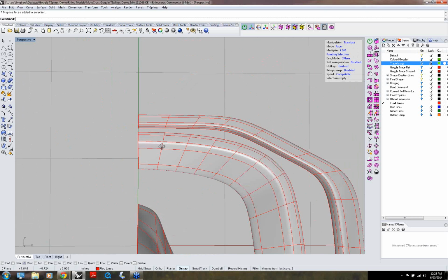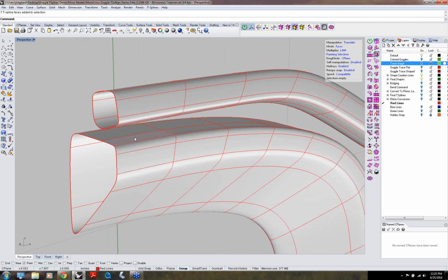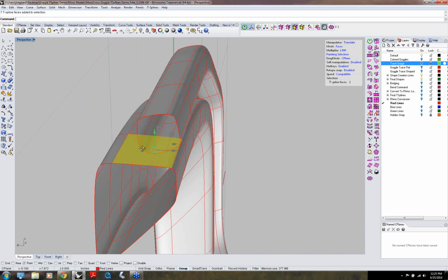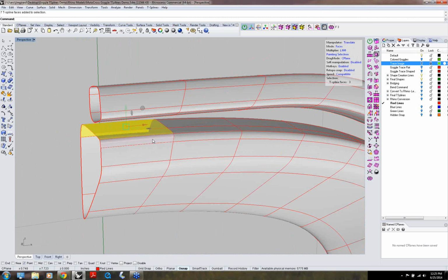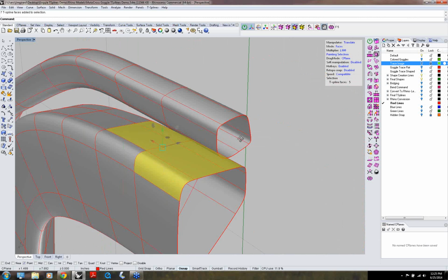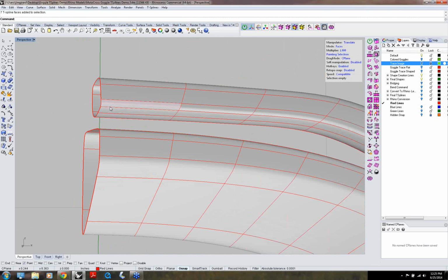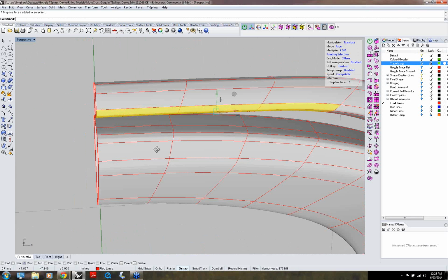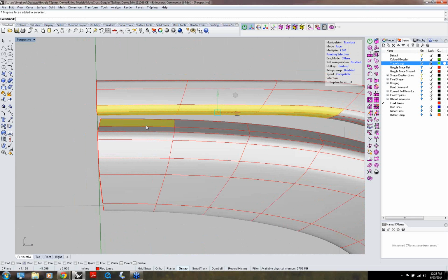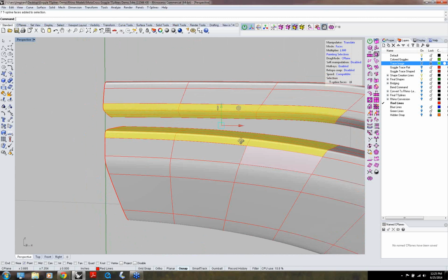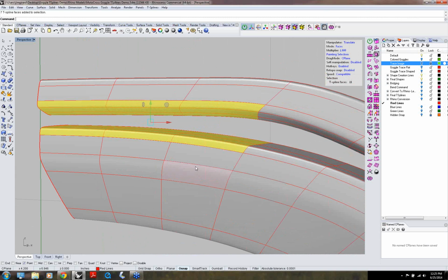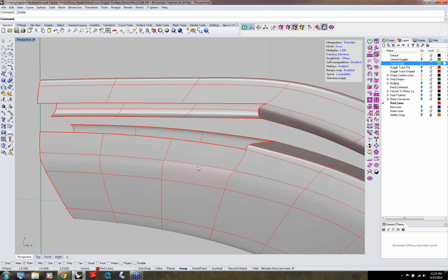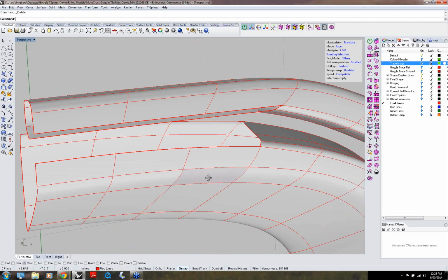Again, I will now go and do the same thing where I want to remove or bridge this top surface. Let's see, I'll pick that. Pick these top 9 surfaces. Now you can bridge the surfaces, but I run into problems sometimes with it, so I like bridging edge to edge, and in that I would ask you to experiment. But I'm going to delete those surfaces, and now I have the same number of edges.